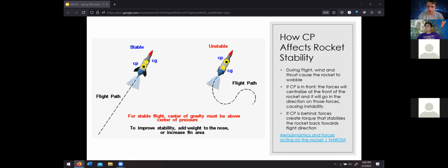When we get over to OpenRocket, I'm sure we'll have a little fact sheet about what you should be shooting for when you design it. As long as you're within 2 to 4 calibers of stability, you're good. But if you're overstable, it'll highly affect the performance of your rocket and make your performance worse. It'll basically always go into wind, such as if you were to push this at all. You see how it goes in that direction? But yeah, fun.